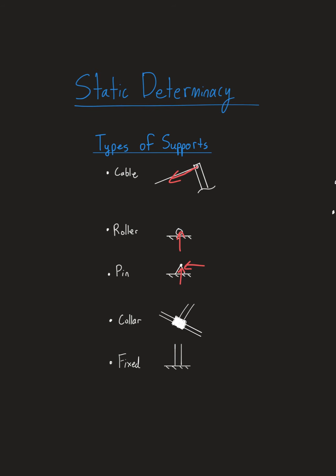Now, a collar is kind of similar to a roller. You don't really see it as much in undergraduate. It does come up more in graduate school, and especially in mechanical engineering, it's a lot more common. But essentially, this collar just wraps around the rod or member that it's drawn on here, and we treat it as a frictionless surface, so it'll just roll along or slide along and doesn't transmit any force along this direction. However, similar to a roller, how there's this vertical force, we are going to have a reaction perpendicular to the sliding direction. So the reaction will look like that.